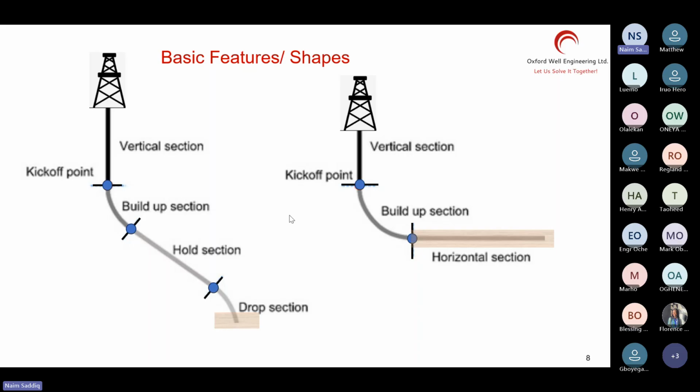Why and how? They have only one casing, 7-inch casing. That's it. And then 8.5 inch out of it. And there you go. Everything is done. And they run the 5.5 inch or 5-inch casing in there all the way to the TD. So it's a fantastic thing that you'll probably be involved with some of those challenging ones.